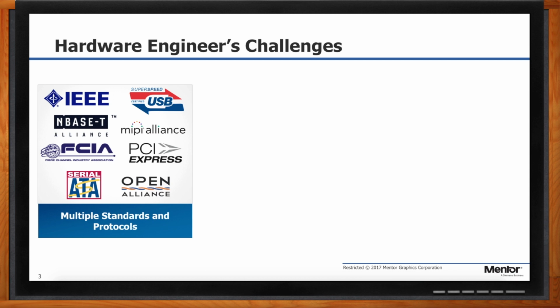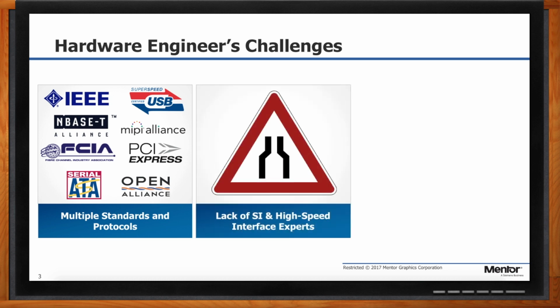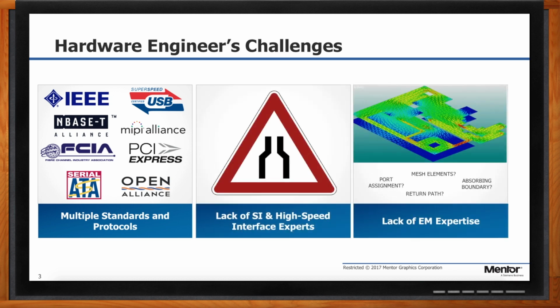And the hardware engineer has a very unique challenge here in that they have to acquire the knowledge to make these protocols pass every time. Sure. On their PCBs. They don't have the signal integrity or EMI expertise to validate these protocols. In DDR, for example, they have to go out and acquire this knowledge. They have to redesign guidelines. They have to read data sheets. Some of these app notes, one I was using for the PCB we're using in the demo today, it was a 206-page app note from an IC vendor.